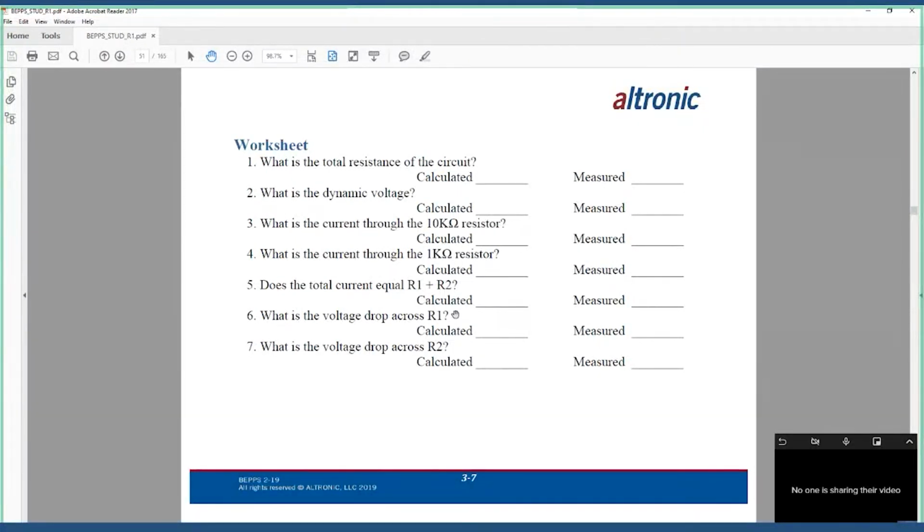We're not going to have a different current per se on these different legs, but we're going to have a total circuit current, right? So to find that current, we're going to take our voltage, which is 9 volts, and divide it by our total resistance, which is 909, correct? And actually, I came out real close. I hit the nail on the head. You're right on spot, 0.0099.